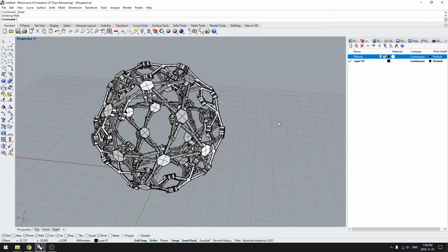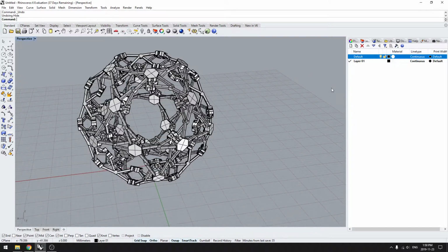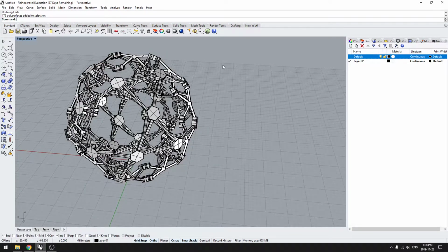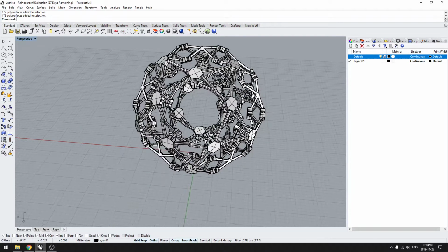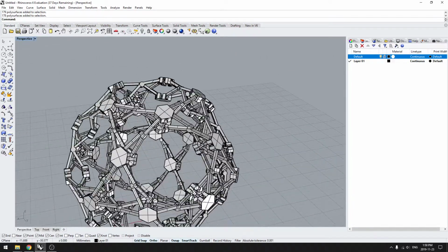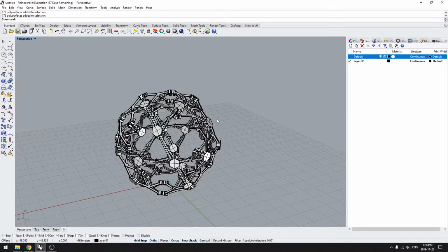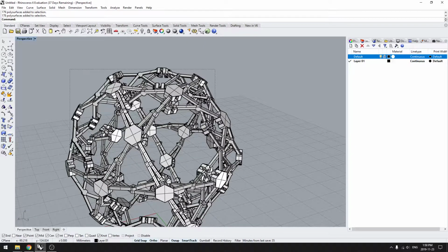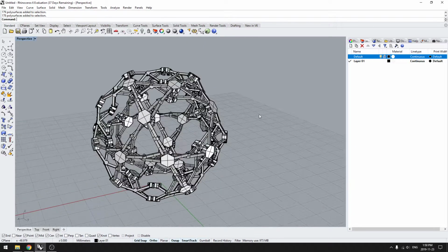So now we're gonna talk about layer locking and object locking. Usually this is all on one layer, right? This is all on the default layer. And if I lock this, I can't select it anymore, right? So this is a good way to have the object be a reference in the background, but not actually interfere with it or manipulate it.